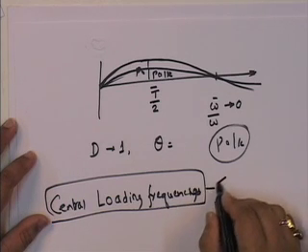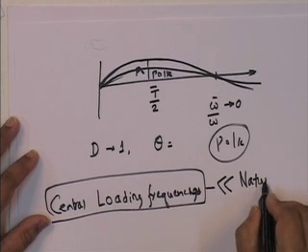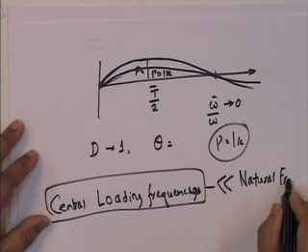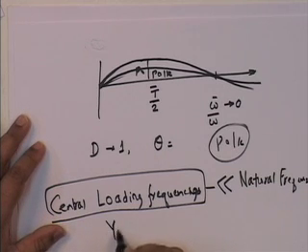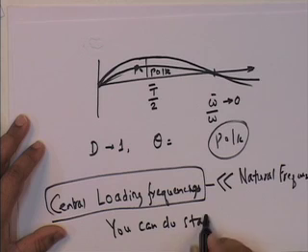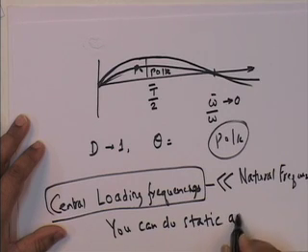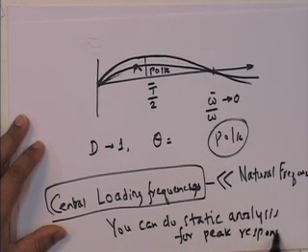If this is very small compared to the natural frequency of the structure, you can do static analysis for peak response.